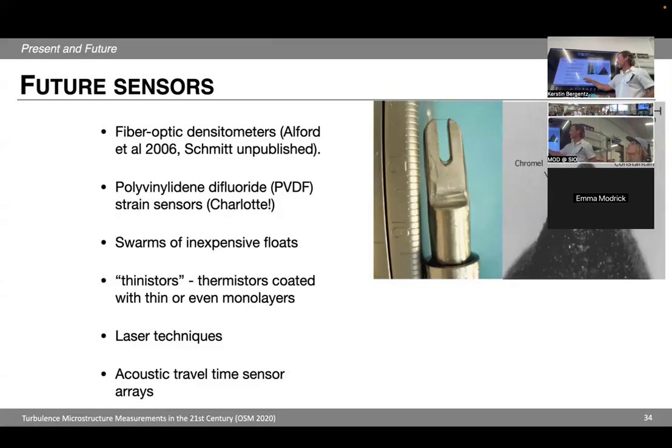He's been looking at whether I can basically do PIV, or particle image velocimetry. So I can make a laser sheet and then try to measure the turbulent motions with that. He's got one of those, and then he's got another one where he's got a strobe and just looking at cameras and trying to put together the flow field that way. So that's what I meant in that random bullet that I probably didn't think about.